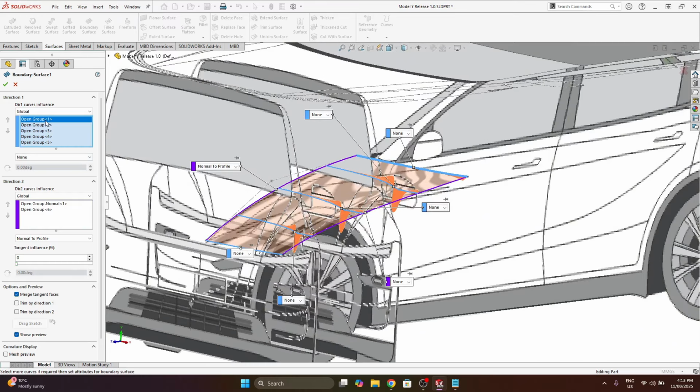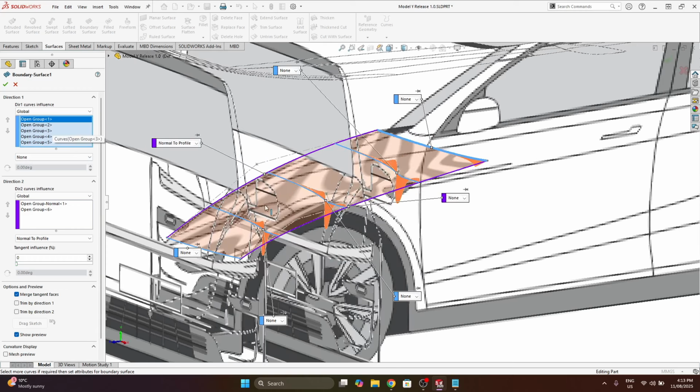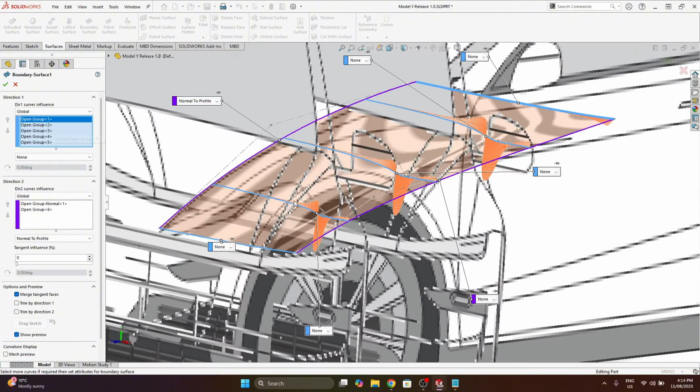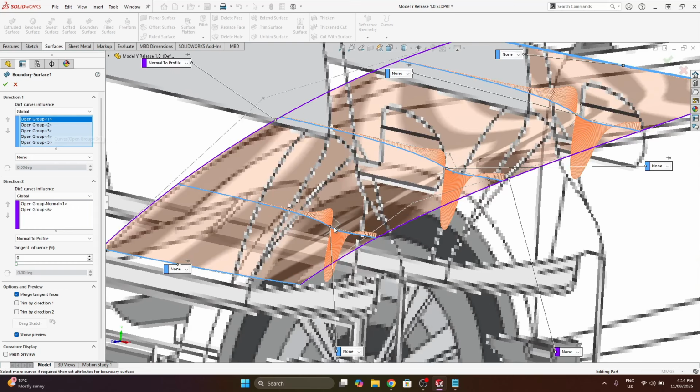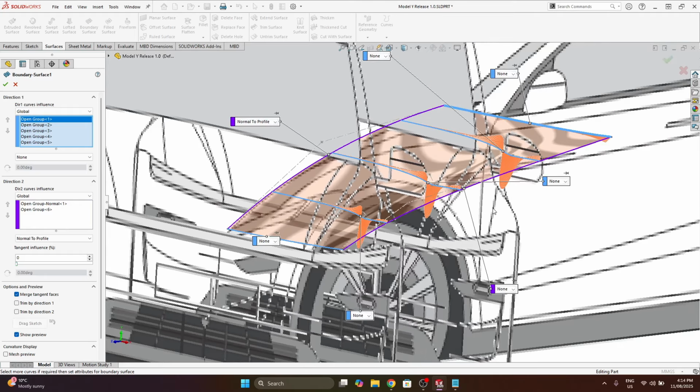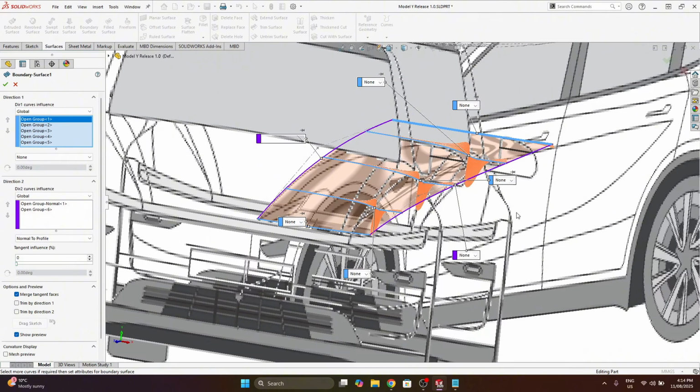And the way I've approached this is I have 5 sketches, each on their own plane. So I've set up planes prior to these sketches. And I'm doing, as you can see, more or less a horizontal line with a slight dip, and that captures some of the detail on the front bonnet. As you're modeling this, it's good to have various reference pictures of the car up, ideally on your second monitor.